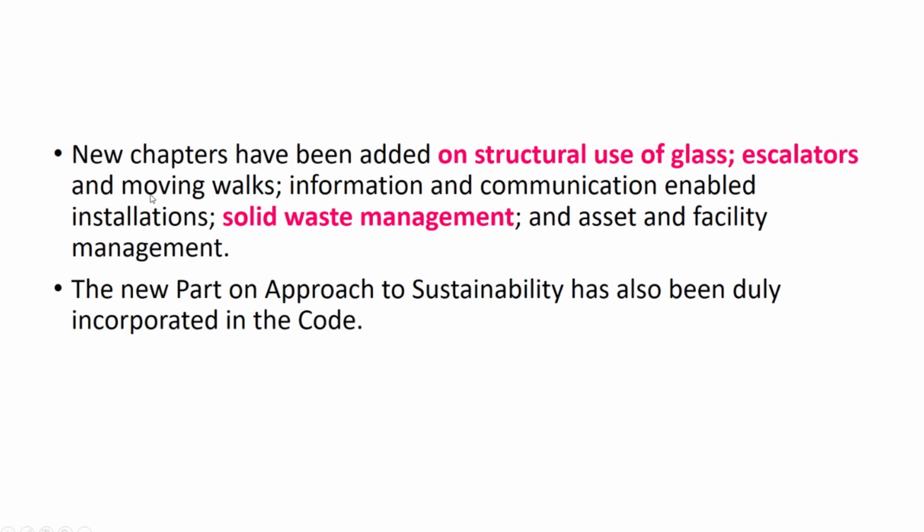insanitary, or not provided with adequate means of egress. That means I don't have a facility of having proper egress from that particular building. I cannot have staircases or any other things by which I can get outside the building, or which constitute a fire hazard.